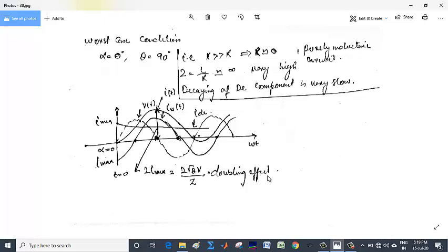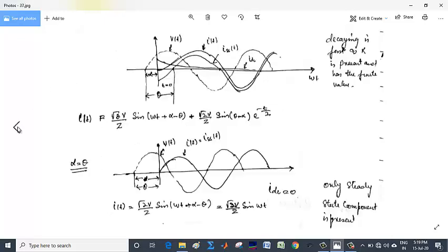So in general, we can say that turning on the circuit breaker, we should always turn it on when the current is equal to 0. That means this current is equal to 0, or we can say the steady state part of the current is passing through the natural zero, like the earlier case we had discussed. In that case, there will be no transient.